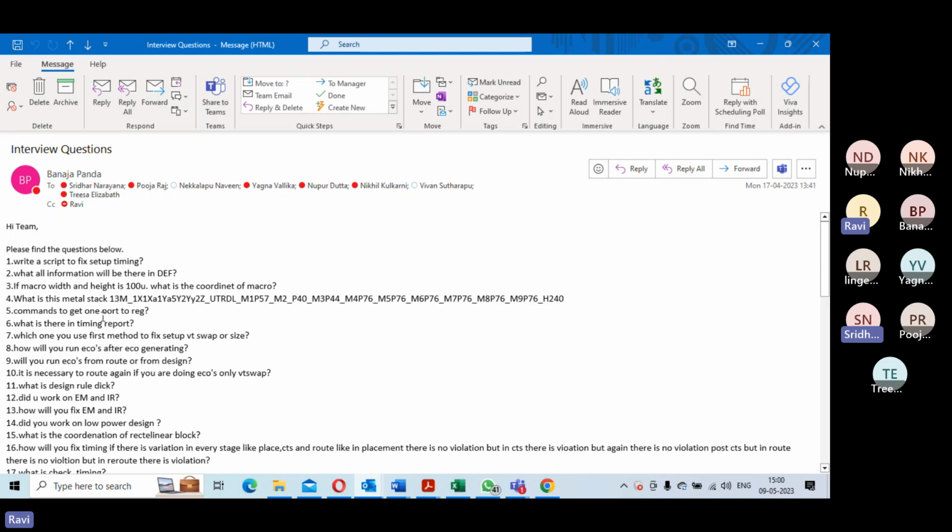And from all those nets, you can look at which net is connected to a pin, and you can get the attribute. If that attribute is a port, then you can report it. You actually have multiple ways. Two of them I have already stated to you.